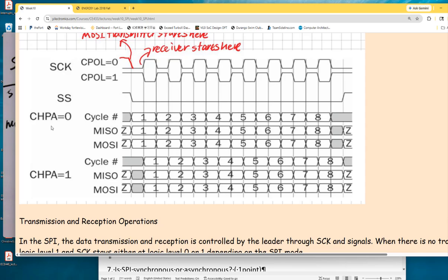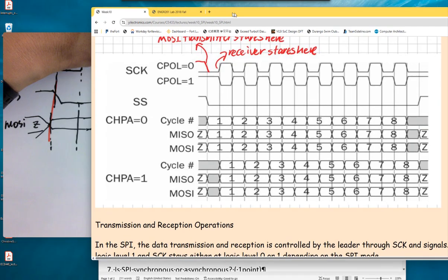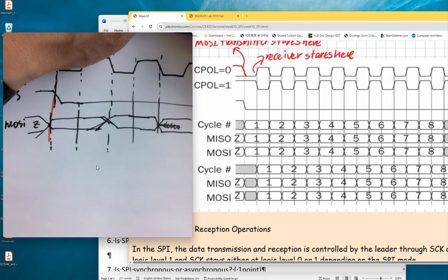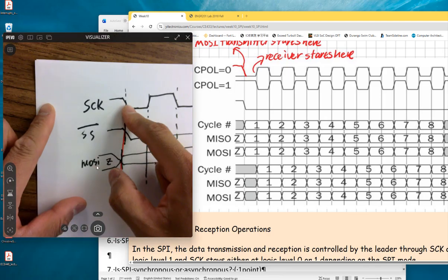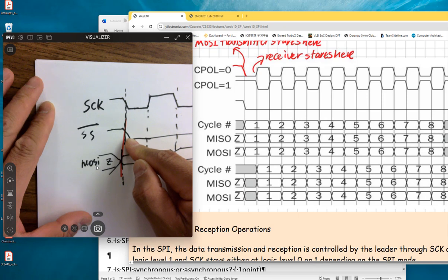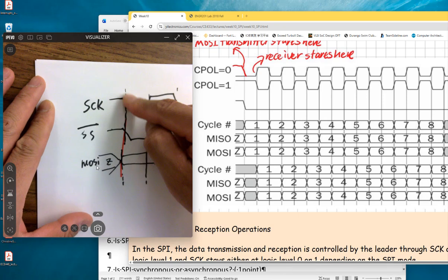And so for the code we just talked about, right? It didn't show a falling edge over here, but it should have a falling edge. Over here is an extra falling edge, and that falling edge is synchronized with the chip select falling edge over here. So they are being synchronized. So whenever the negative edge of the clock arrives, you got a negative edge of the chip select, so it's getting started, right? Chip select is being put down. See? Boom. Boom. Okay? Do you notice that? Two falling edges at the same time.